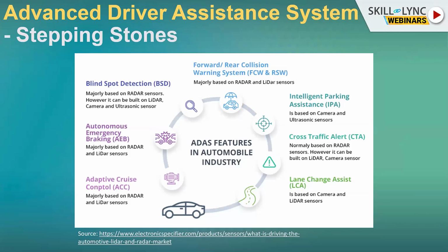It will detect that I might possibly collide into this object or this person, and the reaction time that humans need is actually a bit higher. But since these sensors can predict in advance that a possible collision is possible, it can pre-fill the brake pressure systems and also apply the brakes for us in some cases.